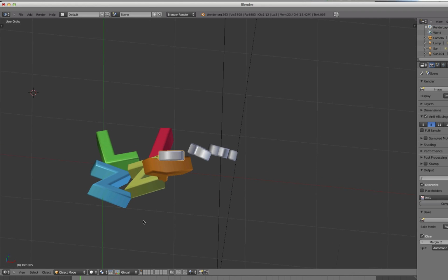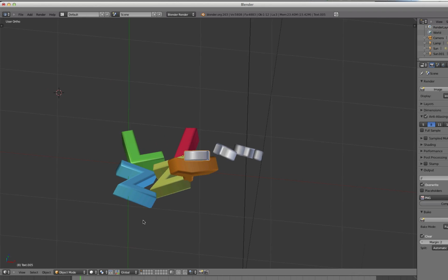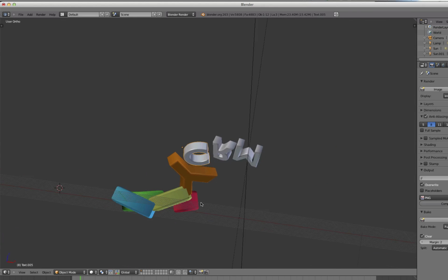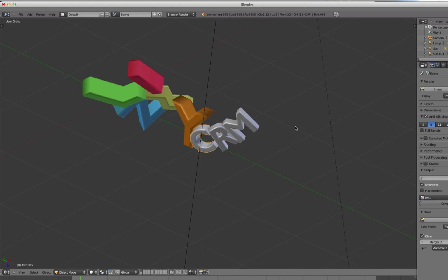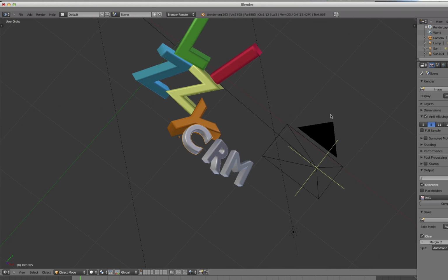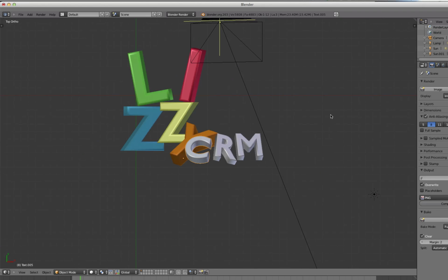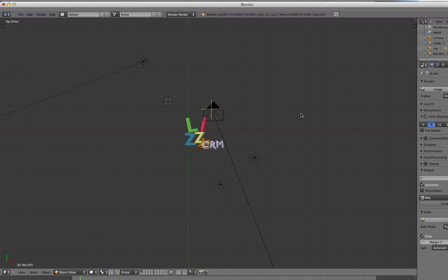I think that there's also a way to get this to allow me to scroll to move around without having to do the function keys or the shift keys, but I haven't figured out how to do it on the Mac yet. So you'll notice here when I hold the Alt key down, I'm in a three-dimensional world, and I'm actually able to look at a number of different angles. Now, to get this in a square format, in other words, I want to look at it straight up and down, I can hit the number 7, and that'll give me a perspective of up and down. I'm basically looking at it from a top view. The mouse scroll wheel will actually zoom in and out. These are light sources. You can put as many different light sources in here as you want.